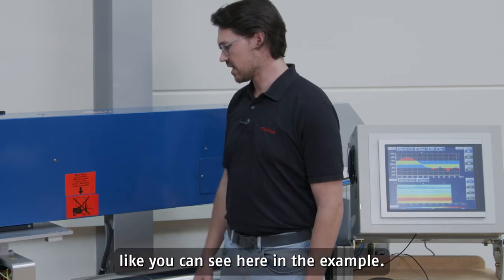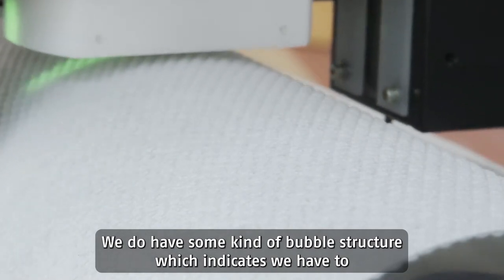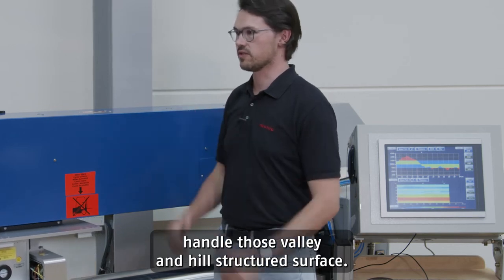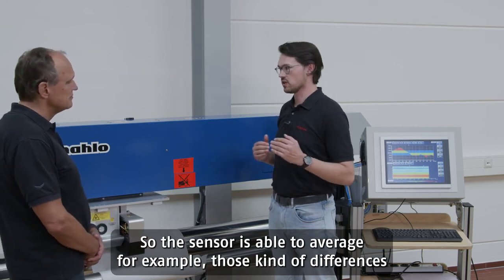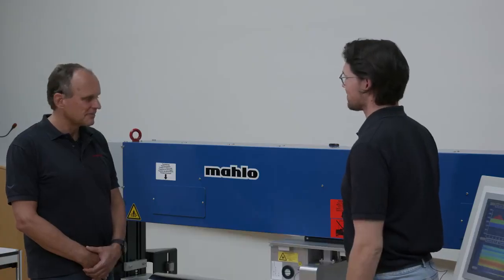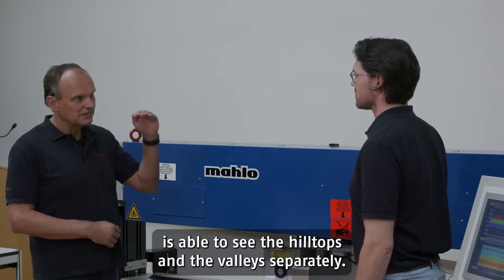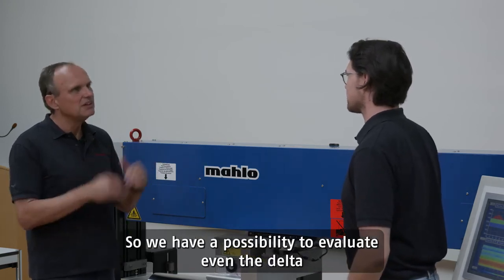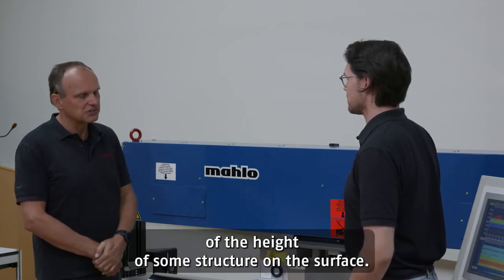Like we can see here in the example, we do have some kind of bubble structure which indicates we have to handle those valley and hill structured surfaces. So this sensor is able to average, for example, those kinds of differences in the structure and also has some other advantages. The line sensor is able to see the hilltops and the valleys separately. So we have the possibility to evaluate even the delta of the height of some structure on the web surface.